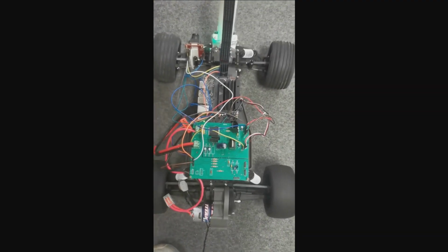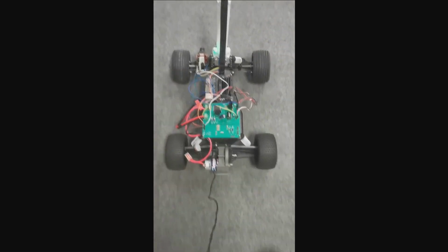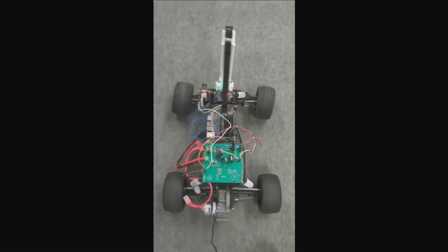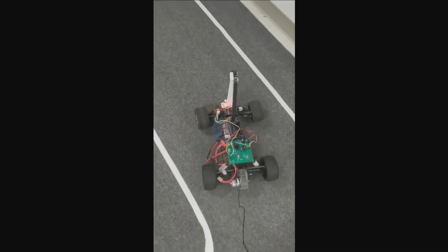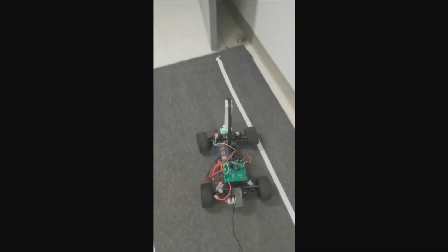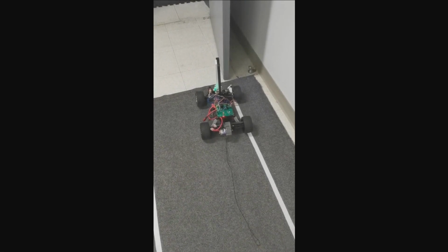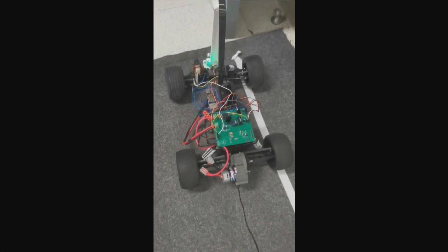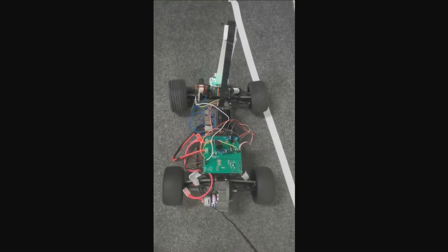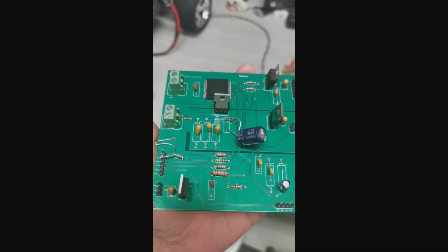During the design phase of our autonomous racing car, we encountered various challenges that required innovative solutions. Initially, we discovered that we had placed the LDO and transistor in the wrong place, which led to the burnout of our circuit. Then, we faced instability in acceleration and cruising speed due to overheating of the transistor and the LDO. To address this, we successfully remade another PCB and implemented heatsinks on these components, effectively mitigating the problem.